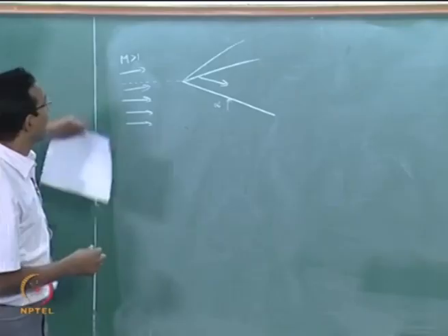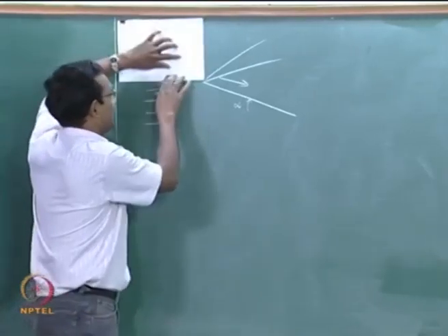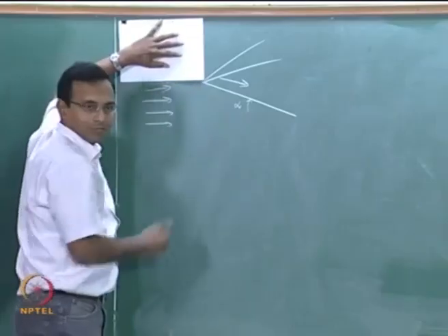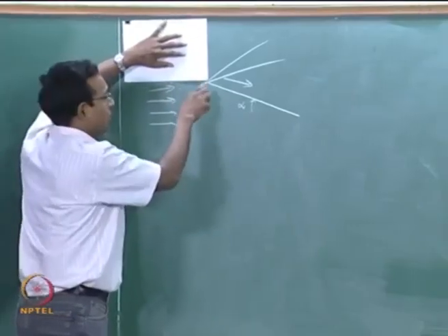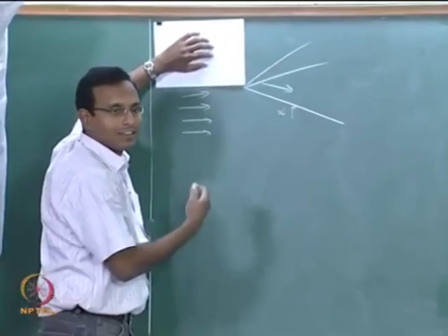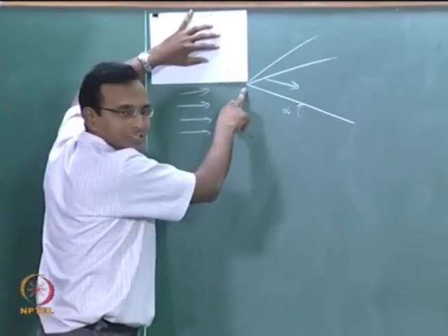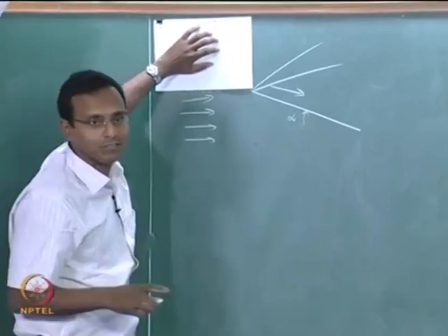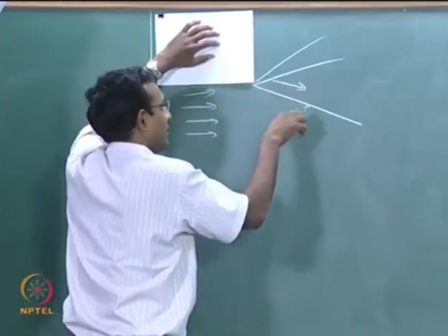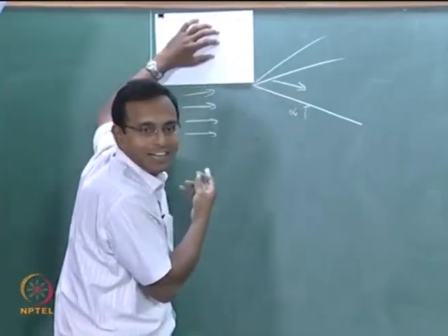Now a little more difficult part, I will block the other side of the dotted line. I am having only this dotted line and flow below. What is this saying? There is a wall which is coming into the flow. This is like a compression and it is a sudden change. So it is going to have an oblique shock, which we covered a few classes before. I have to find the angle. We hope that currently it is not a detached shock.